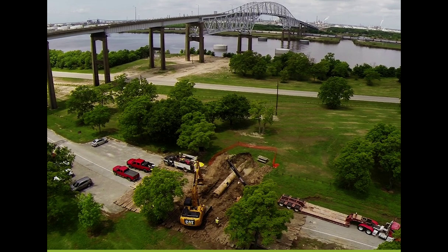This is another good example of ground surface recovery, and you can see when the machine does daylight, there is some workspace required. You've got a track hoe there and a small crane and some trucks and things, but you could typically not see much work at exit other than maybe putting some timber mats down for most of the drive, and then only when the machine was getting close, go over and prepare to receive it.